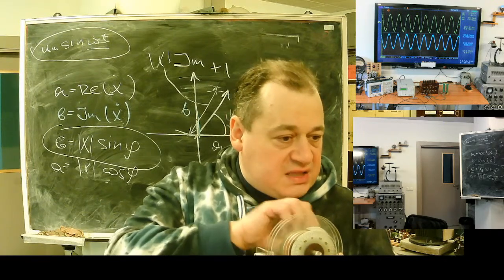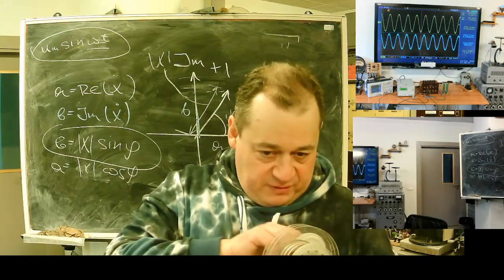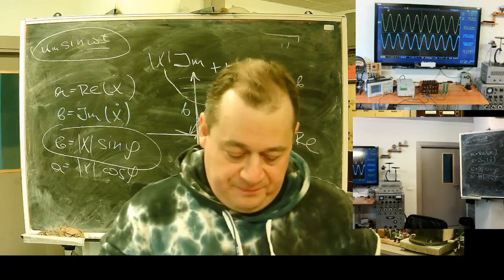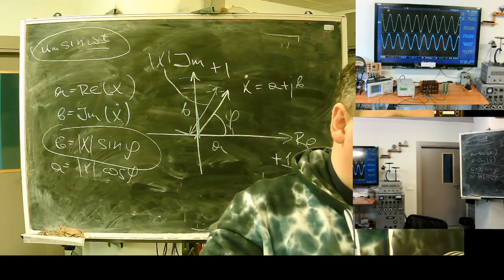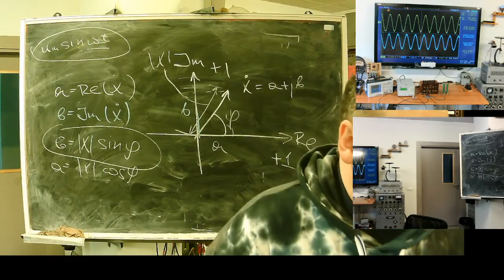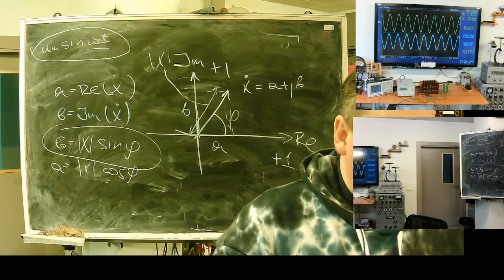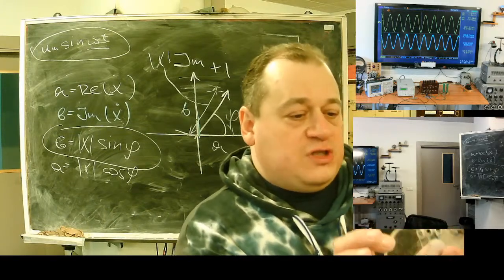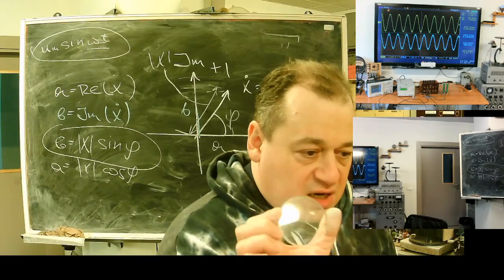Complex plane rotates. For the network, I should rotate it with a speed of 50 turns per second. Yeah? If I take this complex plane from the generator shaft, it will no longer rotate. But the relation between vectors, will it remain? Voltage and current remain, the plane no longer rotates.